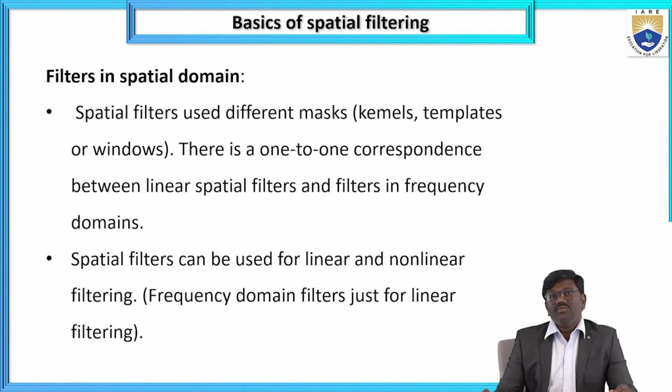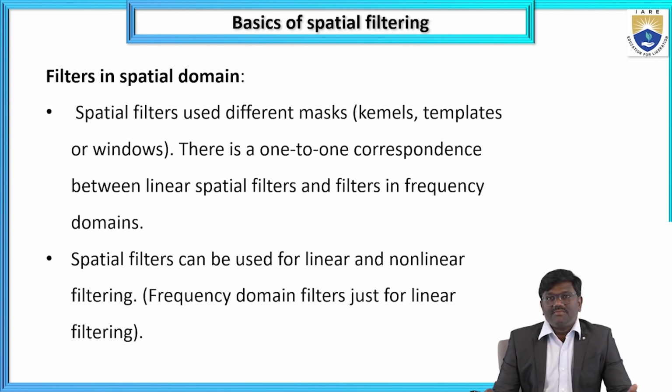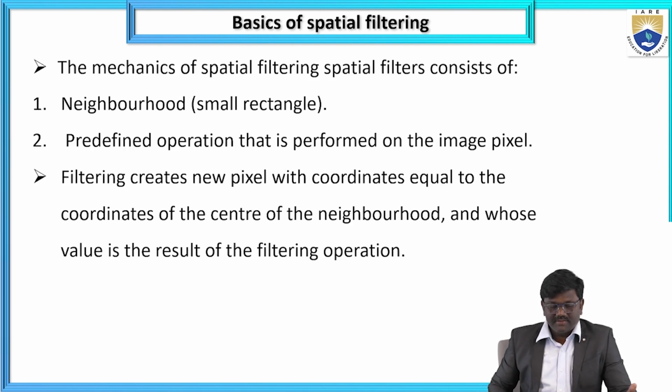There is a one-to-one correspondence between linear spatial filters and filters in the frequency domain. Spatial filters can be used for linear and non-linear filtering, while frequency domain filters are just for linear filtering. That's what we will understand in detail.